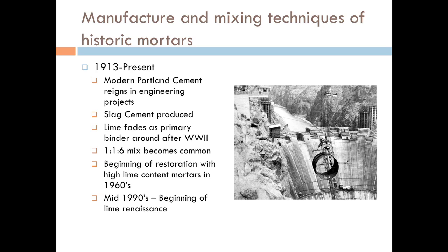So the standards are much higher. And we've been starting to implement these things beginning in the 1990s, moving away from the lime, this 1-1-6 mix, which was specified, or 1-2-9. Again, the first number 1 being cement, second one being lime, the last digit 6 or 9 being sand content, which also, I should mention, follows that mysterious binder ratio, 1 part binder, lime and cement combined or by itself, to 3 parts sand, which also doesn't really work very well, unless you have that extra cement to give it extra strength, and nobody really knows the difference at the end. It's hard and usually good enough.